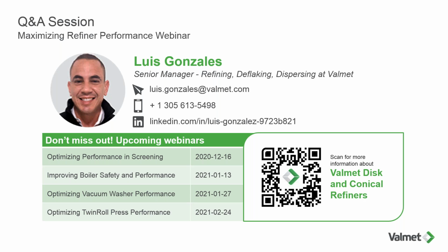What percent of bar height is acceptable? It's another good question, and this is very dependent on where your refiner is at. With these refiners, the wear is in the Z position, so it's going inside the grooves, so you're wearing more and more into the grooves. So there is no change in resulting refining intensity.